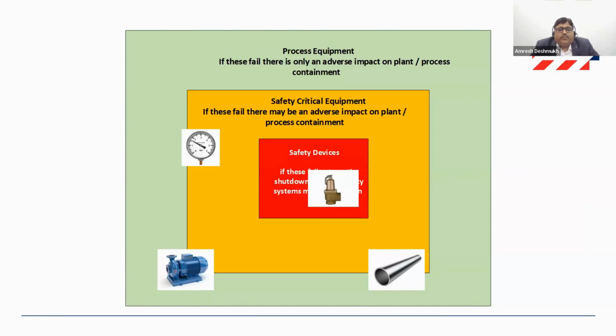So if you look at the pressure relief valve, which is a safety device, its sole function is to release excess pressure from the boiler should the pressure rise beyond a safe maximum pressure. If it failed to operate when required, it can have catastrophic consequences. People in the boiler area or around the plant might get affected.